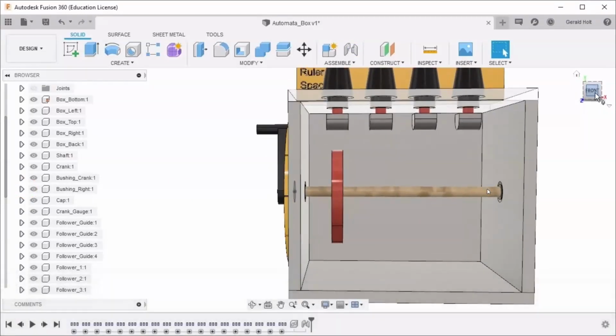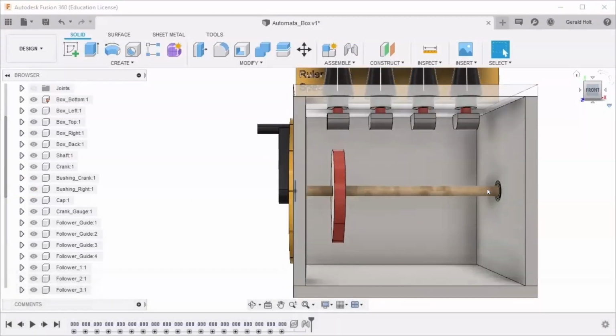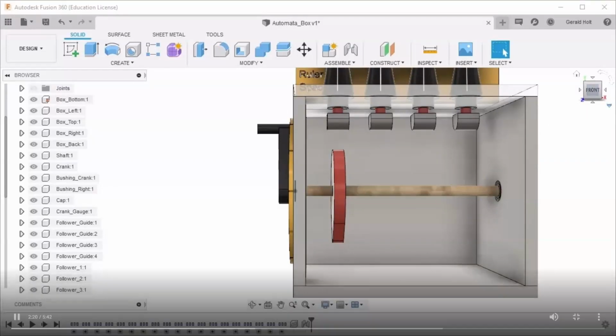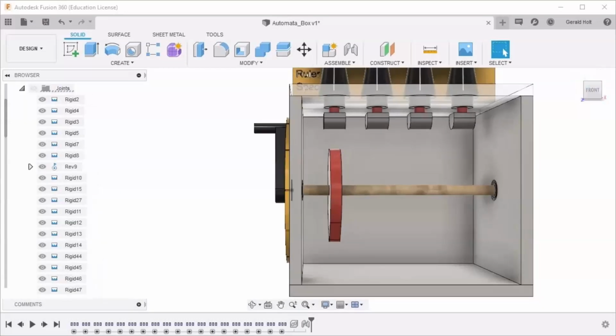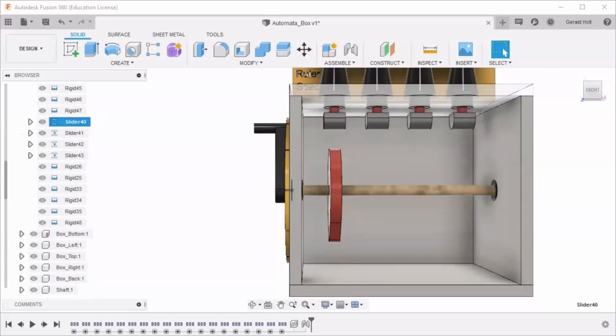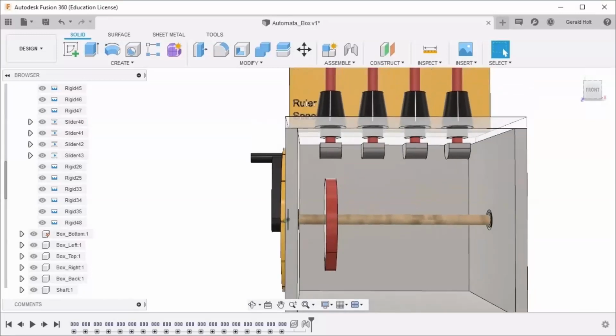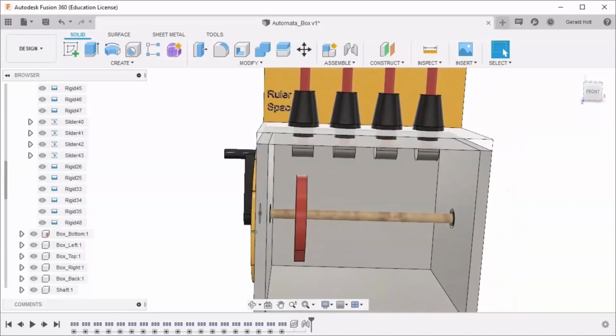The slider joint must be edited to be the current offset plus the distance between the roller and the cam perimeter. This distance was previously calculated to be 0.475 inches. Open the Joints folder again. Find the group of 4 slider joints, then locate the slider joint of the leftmost cam. An efficient way to locate this joint is to select the joint and observe the joint preview information on the model. Position the model to see the follower guide and the roller.